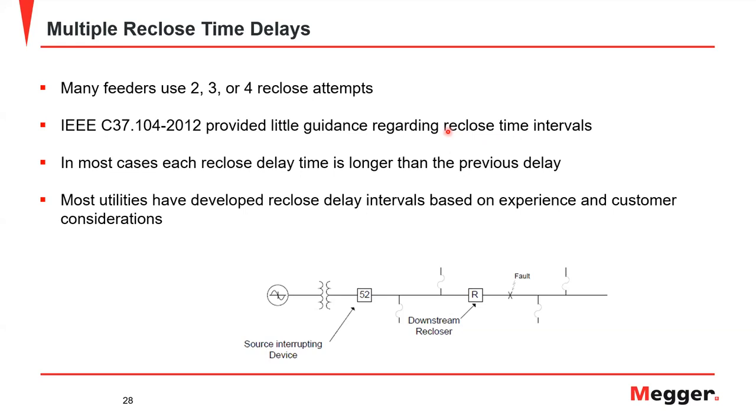How is it possible to figure it out? Well, the first one is understood. The fastest that you can reclose on any fault is your 20 cycles required for gas dissipation. The real answer just comes through experience.